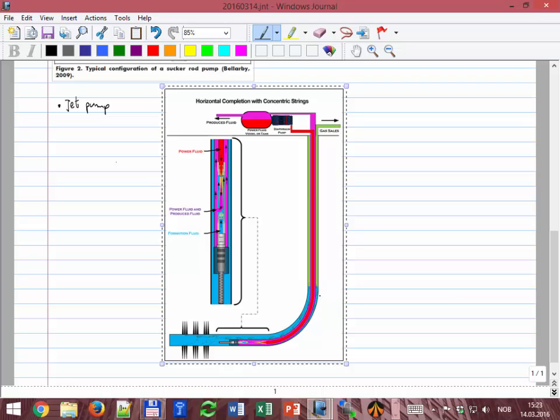through a very restricted section, like a throat. It has an expansion and converging section. And in this section, when the fluid goes so quickly, the velocity goes up very quickly, and the pressure goes down very quickly. And as the pressure goes down, that is kind of sucking materials to this low pressure point. So the fluid in the reservoir is getting sucked by that stream. So in this case, it's going out here and into this throat, and then it's kind of going up through the